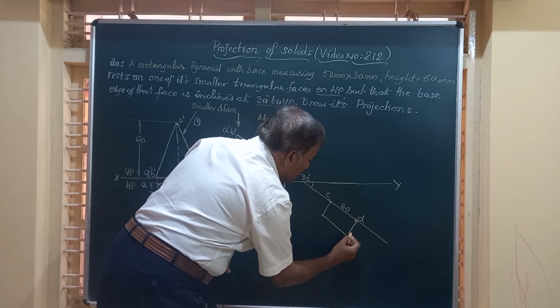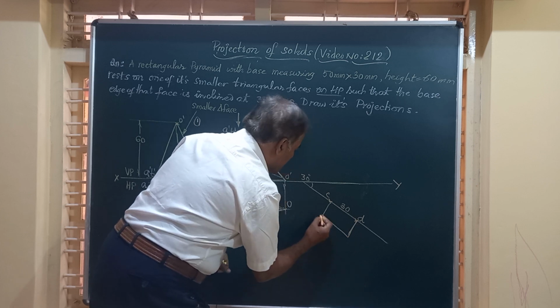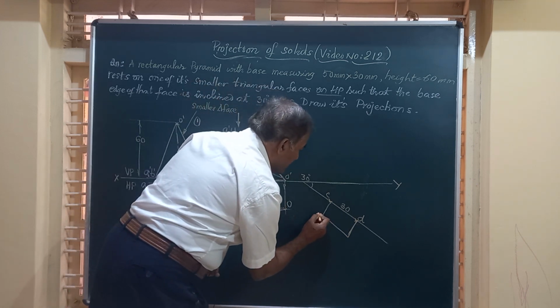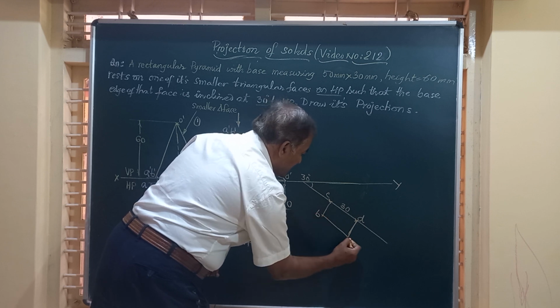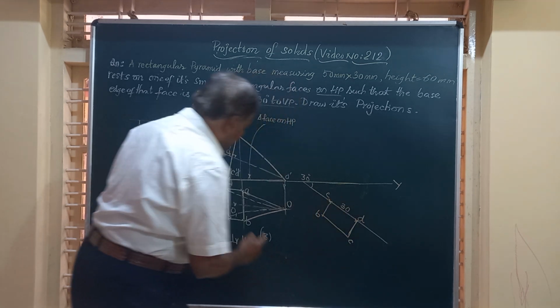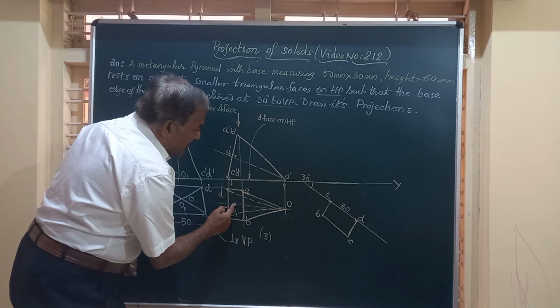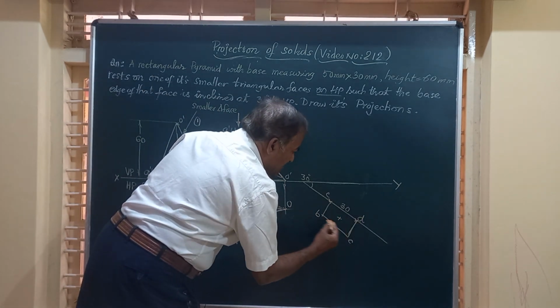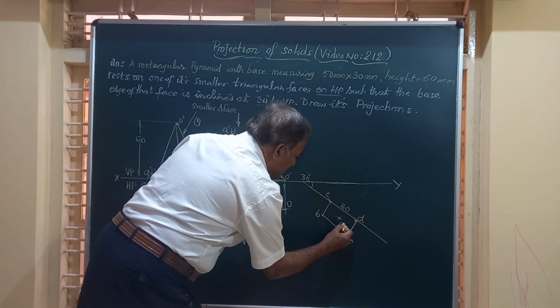So this is going to have a dimension of this much, this CB in the top view. So this is B, this is C. Friends, you have got ABCD the base. You locate the center. This is center O. By drawing these diagonals, you can call this as O1.